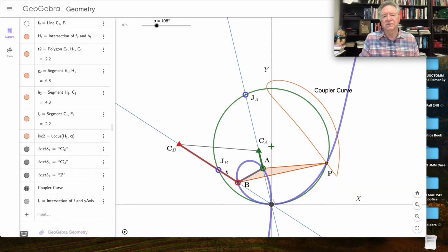So what we have here is the moving pivot of the output link, the moving pivot of the input link, and there's nothing that really distinguishes them, but we're just going to set their color to green so you know input versus output. The triangle is the center of curvature, but for our linkage it'll actually be the physical fixed pivot.